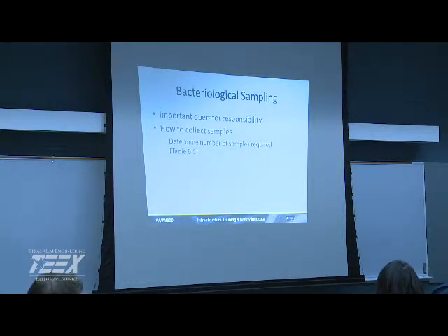We're going to talk about our site sampling plans and the importance of it, and then how do we get a good plan in place. One of the things that we really need to consider is how do we represent our system well? So we want to designate areas, but we want to have alternate points also. And not only do we want to designate an address, but have something more specific, where you say, I'm pulling it from this hose bib. Make it very descriptive.